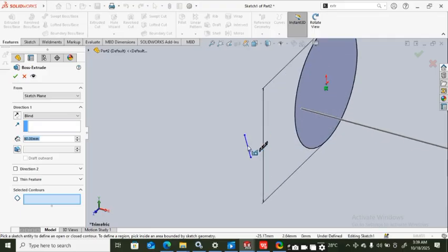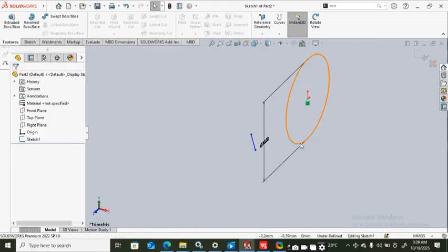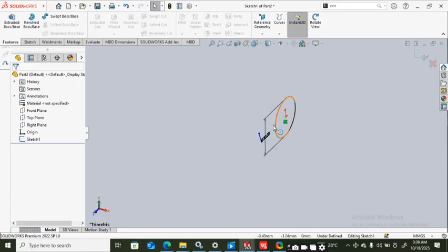It's this particular line. This line is an open sketch, right? It's an open sketch. It's not going to form anything. It's preventing it from working. The only way this thing could work is to make sure that this now becomes a closed sketch. And how do we ensure that this is a closed sketch?